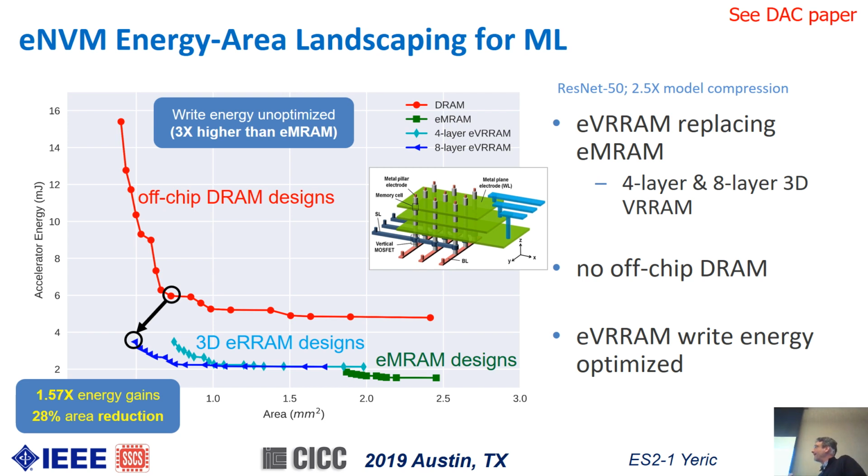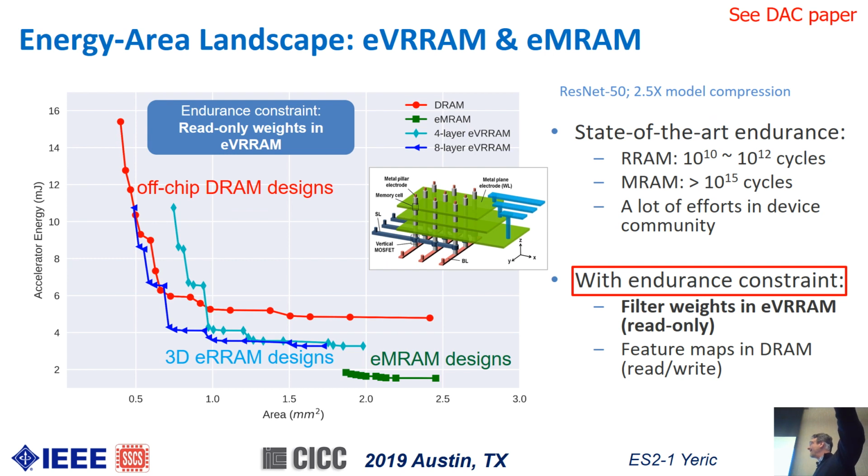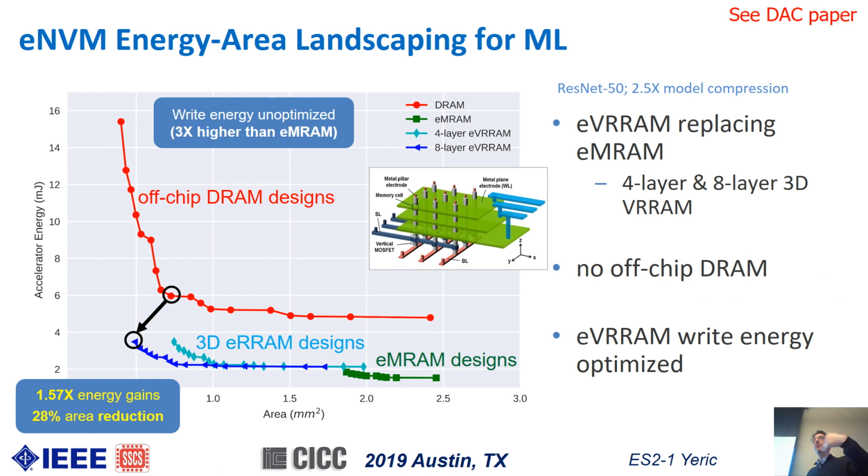But that's not accounting for the fact that RRAM doesn't have very good endurance. So if you do the things you need to do to deal with the small endurance, then those curves don't look that great anymore. For some of the larger instances, yes, but you really have to pay attention to how you deal with non-infinite endurance in these memories, and you will find that there are cases where they're not really that compelling, and cases where they are, but a fair amount of work to do to get to that point.